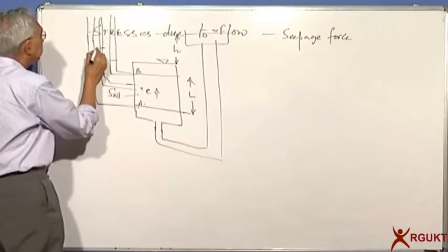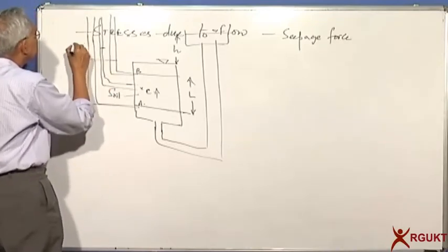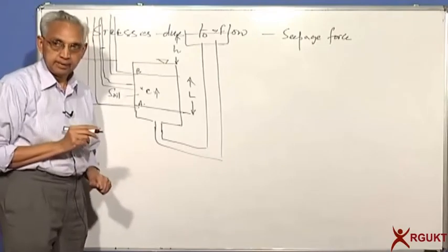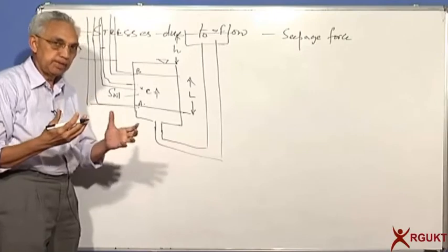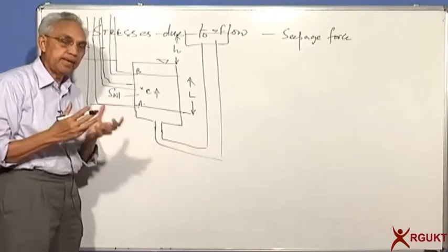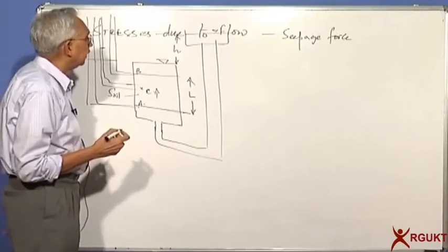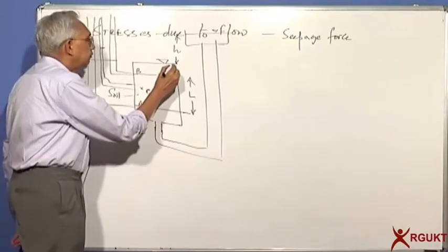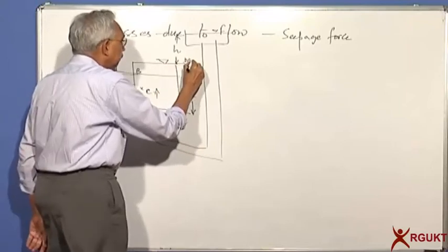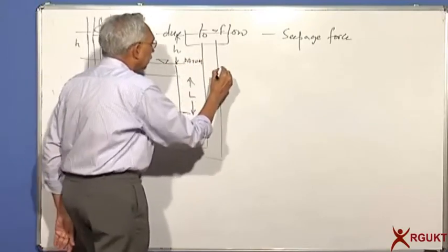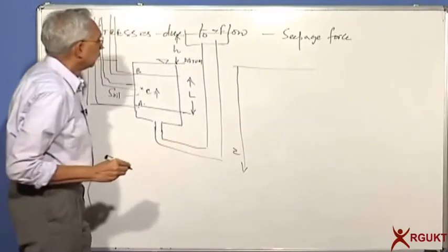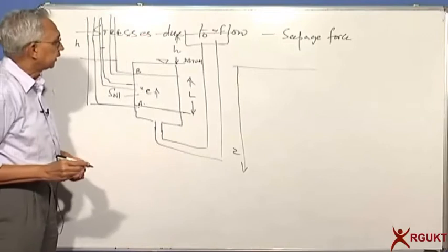So this difference between upstream and downstream is H, which is the net head loss. Let us plot the total and effective stresses, pore pressures, etc., to see what is happening to these stresses. Suppose I want to plot with respect to this point. I take this as a datum. This is the depth. How does the total stress increase?